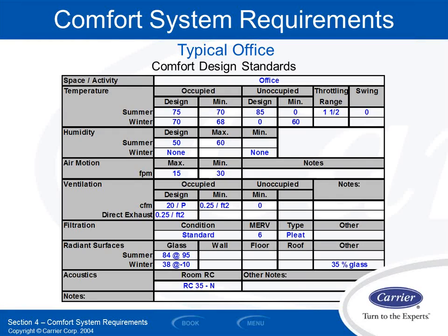super, super cold temperatures. In some cases, like in the state of Illinois residentially, you have to design for 75 cooling. You're not allowed to design for something lower. And if you have a good inspector in your town, he's going to flag that and make you redo the load calcs with a 75-degree temperature. Likewise, on the heating side, depending on your code, it's going to be 70 or 72 degrees there.